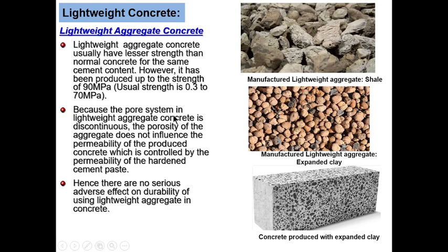Now, because the pore system in the lightweight aggregate concrete is discontinuous, the porosity of the aggregate does not influence the permeability of the produced concrete, which is controlled by the permeability of the hardened cement paste. Because of this, there might not be serious durability problems in lightweight aggregate concrete.